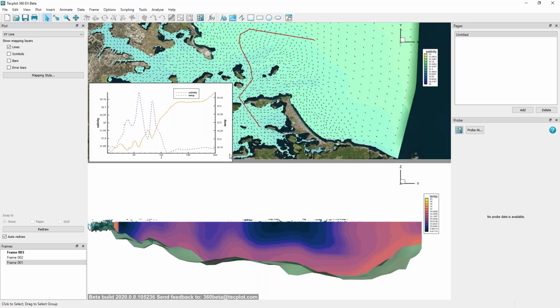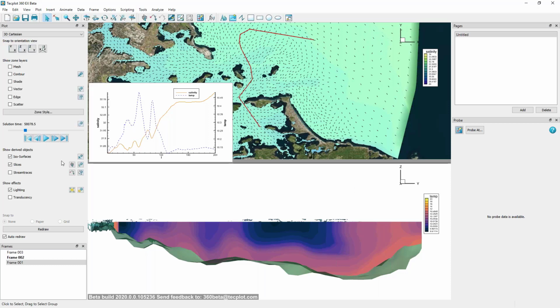I think the best way to compute distance along that line is going to be using our Python API, and at each point you're able to get the x and y values and compute distance using the Pythagorean distance. I don't think that analyze option is going to work that you showed there. Okay. We can certainly help with authoring of a Python script if you need distance. The vertical transect tool that I mentioned earlier does compute distance along the line for you, so you could take a look at that.